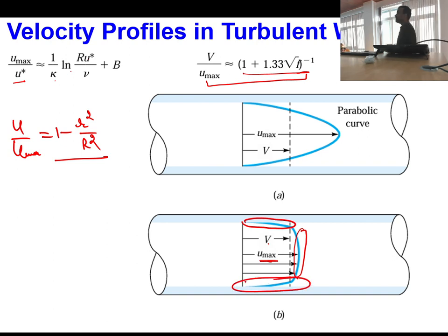Okay, so this way, when we will be increasing the diameter of the pipe, what will be happening? Only the gradient near the wall will be influenced, and in the center I will not be having more occurrence of the gradient. So that way I will be finding more reduction in the pressure head in case of turbulent flow in comparison to the laminar flow. Is this one clear?